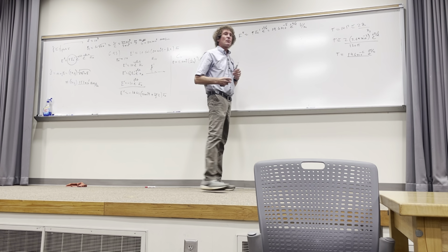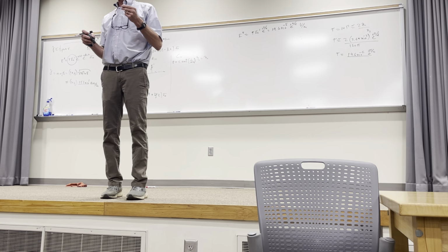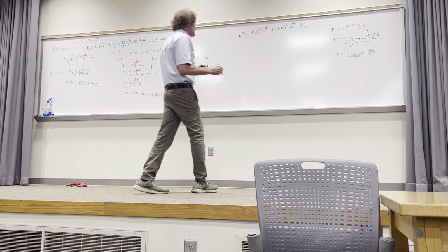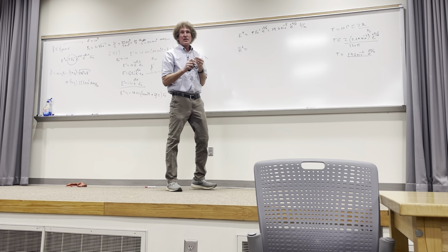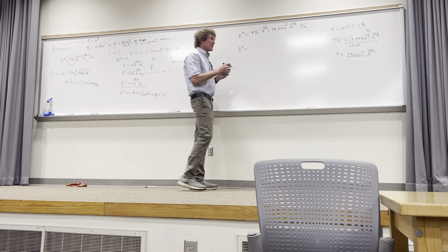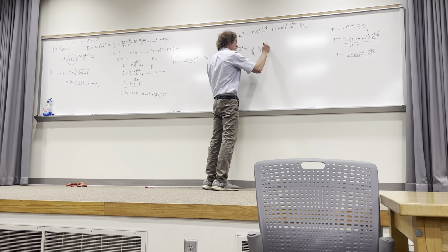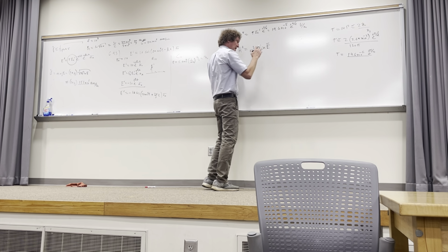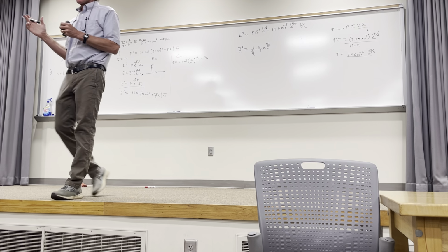These are all kinds of questions that I'll ask you on the final exam. I'm trying to prepare you. All right, think about it. How would I get the H field that's transmitted? Well, it's a plane wave, right? It's propagating. If I wanted the H field, I could say it's 1 over eta, right? And then direction of propagation crossed into the E field if I was in the phasor domain. Do you all agree with that? That'll work. That'll work every time.